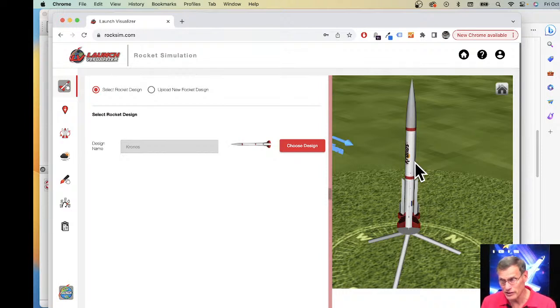It's actually more like a medium wall. If you think of a BT-80, which is 2.6 inches in diameter, its wall thickness is less than 0.02 inches, where a 3-inch tube is probably triple that thickness. So it's a lot thicker. It's not as thick as a high power tube, but it's much stiffer than what you'd think. Okay, so hopefully that answered Alfred Indy's question.